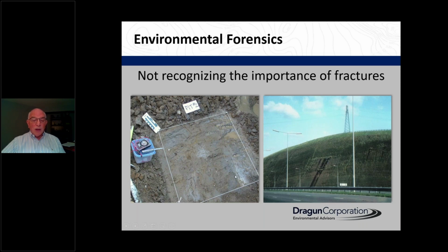In this test pit where we were looking to see the nature of the clay, you can see these wet areas, and that groundwater is coming up in those fractures. So groundwater can move a lot quicker in fractured clays than it can in massive clays.